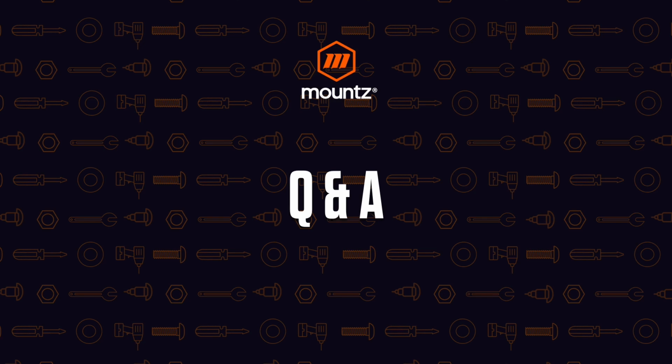Morning, Dave. One of the questions we had was, can you confirm again how many workflows or fastening sequences can be programmed and stored with it? On the unit itself, there are 15 different models that can be made, or 15 different assembly processes that can be made up of the 15 different presets that are available. And within each model, it can have 20 steps. If you need to go outside of that, there are ways that we can program it to do that, but that is by default what we have on the controller.